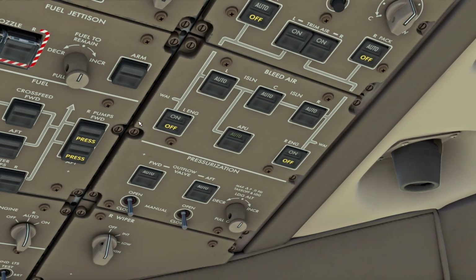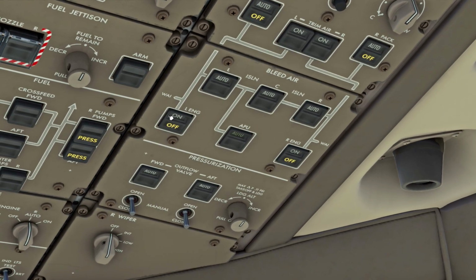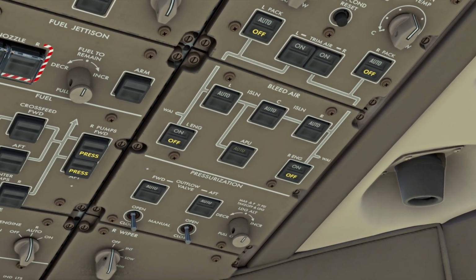So there's a lot of system logic behind here that will operate automatically in any situation. The bleed air switches, basically the valves will open when bleed air is available from these sources. So the engines provide bleed air for this entire system. That's air coming off the engine, or the APU can also provide the bleed air. So we'll just leave these switches as they are. As we start the engines, you will see that the off lights get extinguished and supply bleed air to the PACs, and it will all configure automatically.